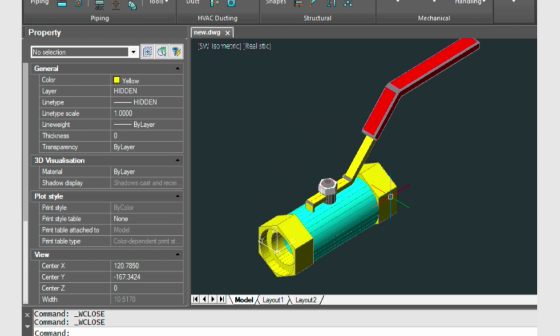I'm going to do this in two videos. The first video is going to show you how to add this block into the bill of materials, and then the second video to follow in a day or so will show you how to paste this block into a new drawing and then carry with it all those bill of material settings so you can cut and paste this block without having to redo the fitting over again when you need it again.